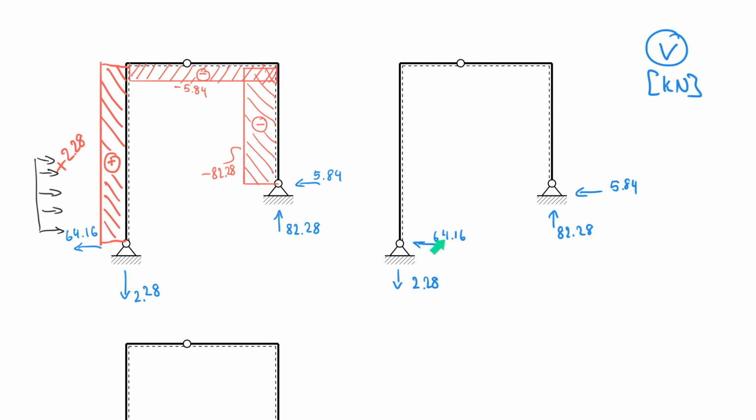And now I wish I could rotate this picture by 90 degrees, but it's virtual, so that doesn't really work. But I want you to imagine to actually look at this as being on the bottom, right? So remember what we've done in the past when we had horizontal members. We always said, hey, if the reference fiber is on the bottom, we can start on the left side and then follow our arrows. So that works here as well, because effectively this arrow is under the reference fiber, and so I can just follow that arrow. And remember, there's the evenly distributed force here, so I'm going up, and then I'm going down, down, down, and then nothing happens, and it goes back to 0.